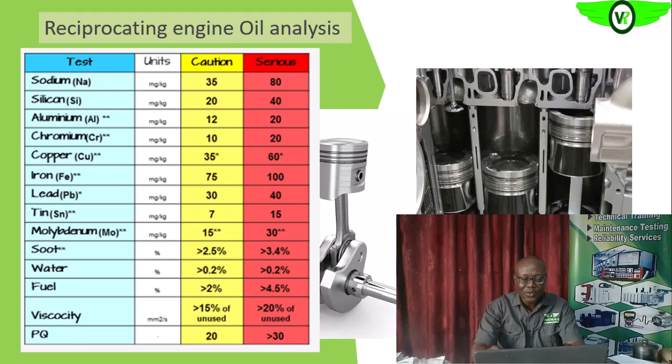And like we said earlier, before all of this will even show up as increased vibration, it will mean that the wear has deteriorated to a very large extent. So as you are carrying out the wear particle analysis, that is the oil analysis, before it shows as an increase in vibration, you would have seen it in the oil.